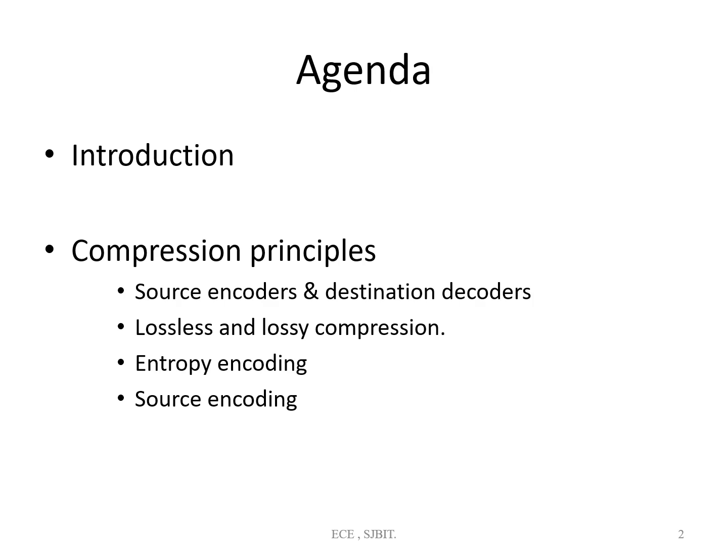Coming to lossless and lossy compression methods, the compression algorithms can be classified as being either lossless or lossy. In a lossless compression algorithm, the aim is to reduce the amount of source information to be transmitted in such a way that when the compressed information is decompressed, there is no loss of information.